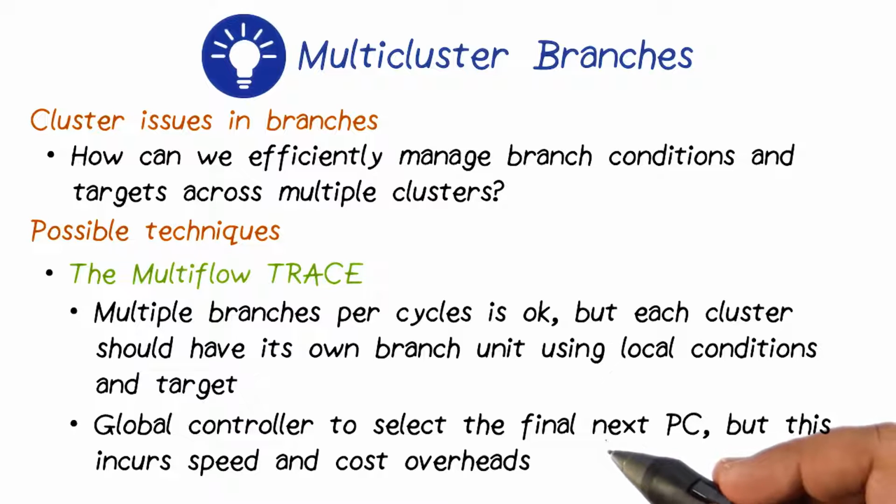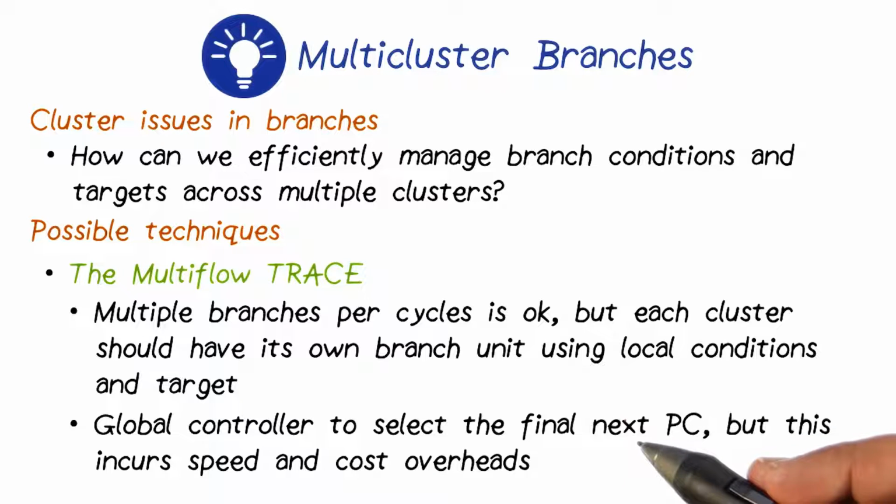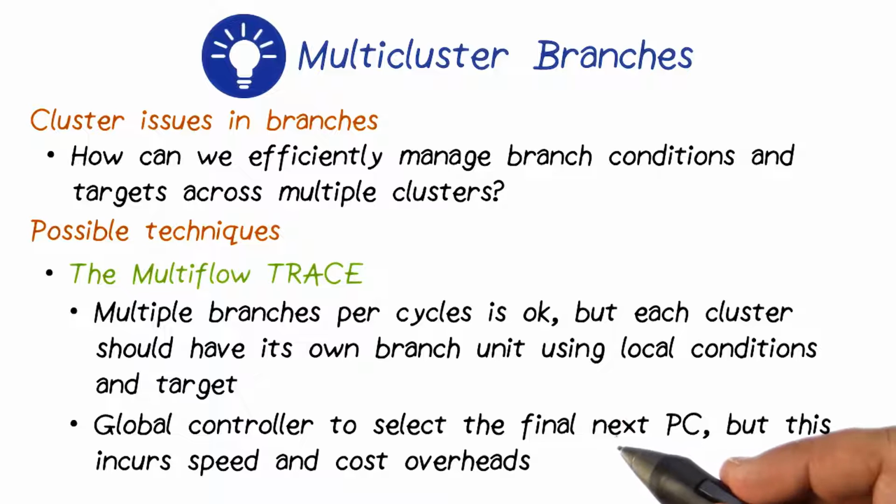You can see that predication had to be implemented here across different clusters, and that determines the destination PC. Now this can cost overheads and slow down the clock, but it also has the benefit that multiple branches now are not sequentialized and can be implemented using a multi-way branch, significantly getting rid of all those delay slots and sequentialization of those branches.